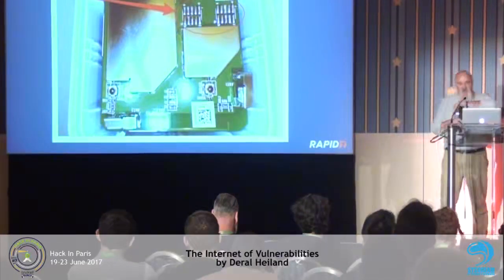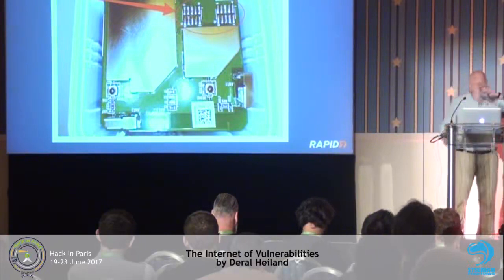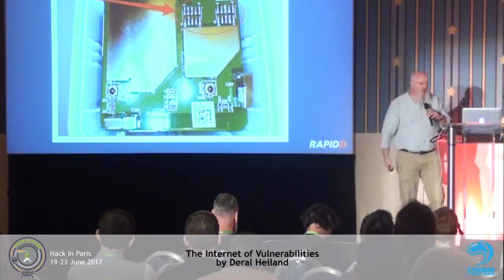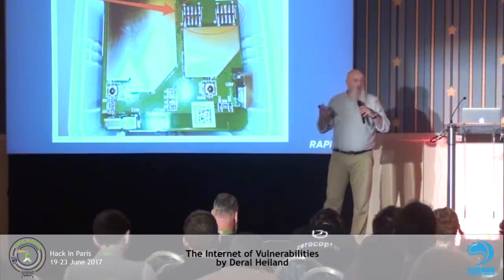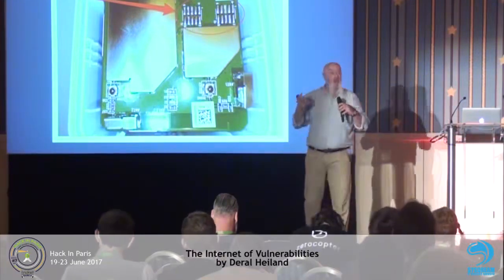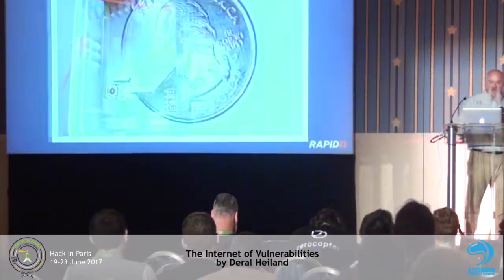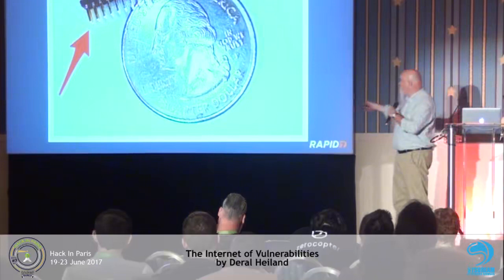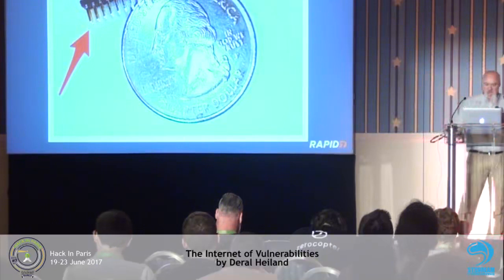So, we've got to get into a little hardware. Not too much, but a little bit here. On the home device, pop it open. The first thing I see in here is a couple of landing pads. What do we think these are? I'm hoping they're a simple UART connection, and they turned out to be. The next thing we want to do is find some connectors. These were gull-wing connectors. That's just to give you an idea of the size. It's really small, like 1 millimeter pitch.